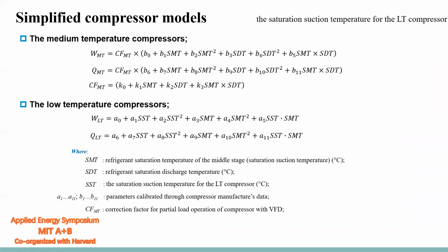We also use a simplified regression method for the compressors. The inputs include saturation, suction, and discharge temperatures for these models. We can see that there are two sets of regression parameters, A1 to A11 and B1 to B11.